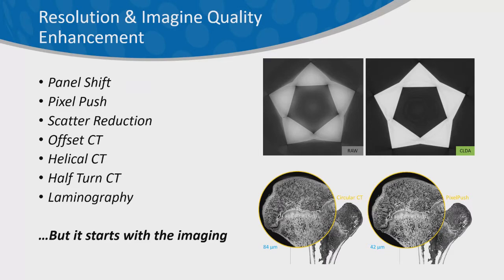That's typically one of the first things we do when we encounter a circuit board where we want to generate some data from it: determine what resolution we need. We might know what the layer thickness is, and if we do, we can determine what our resolution has to be. We can also do quick test scans to measure what some of these small features are that we're going to need.